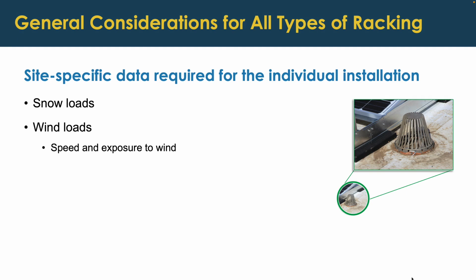The mounting structure systems, the racking manufacturers will help us with this design to make sure that we meet all the wind loads of our location. Do we live in a place that has a seismic load consideration? So do we have earthquakes and have to consider that the building might move? And how do we make sure that the array is going to be fixed and meet our seismic load requirements if they exist in a certain area?